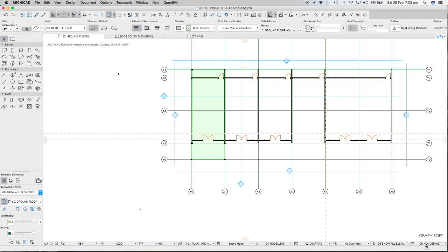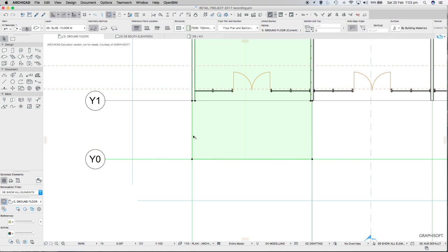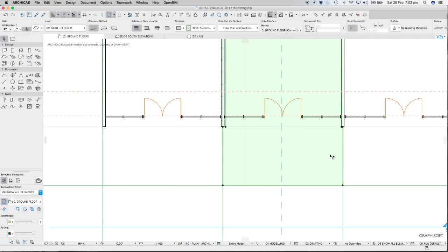So we'll select that wall, and I'll maybe pick this edge here, pet tool, go back to drag, make sure it's in drag mode, and we can drag that one across. Make sure you use your control key to get a little plus sign to copy it, option key if you're on Mac, and we'll take it through to there. So I've now got two slabs.